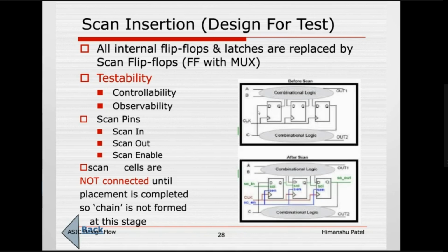What we have done is we stitched all these three flops in a chain format, like a shift register format. I will discuss the scan session again, but I'm trying to explain here itself what we do in the scan session. With this small logic, I'm trying to explain to you guys. Try to concentrate and ask me if you have any queries.